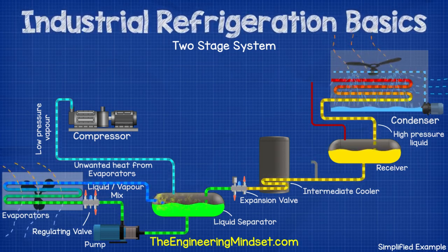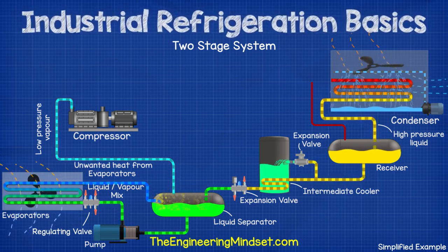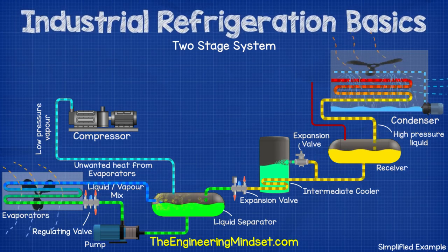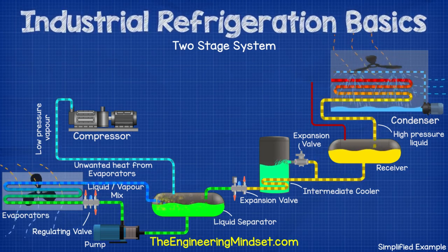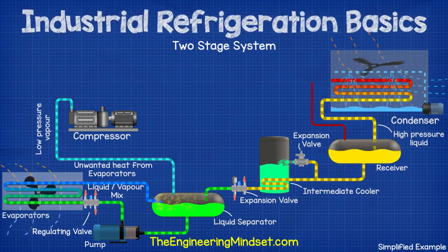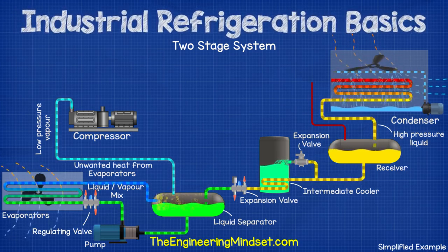separator. Another stream of refrigerant comes off the main line and is sprayed into the tank via an expansion valve to produce a cooling effect. As it is sprayed and evaporates into the tank, it cools the submerged coil. This subcools the main flow of refrigerant inside the coil before it flows to the main expansion valve.